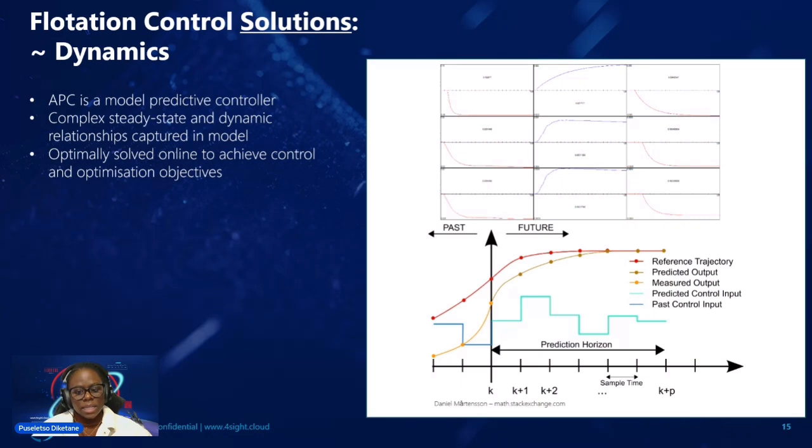Now, this particular technique allows for the time delays, your steady state gains, and more of your control parameters of each of the flotation cells to be modeled individually in terms of the operations and control operations of your process. And this will ensure that we appropriately account for them within the controller in terms of making decisions on how best we can achieve the control objectives that have been set out for your flotation circuit.